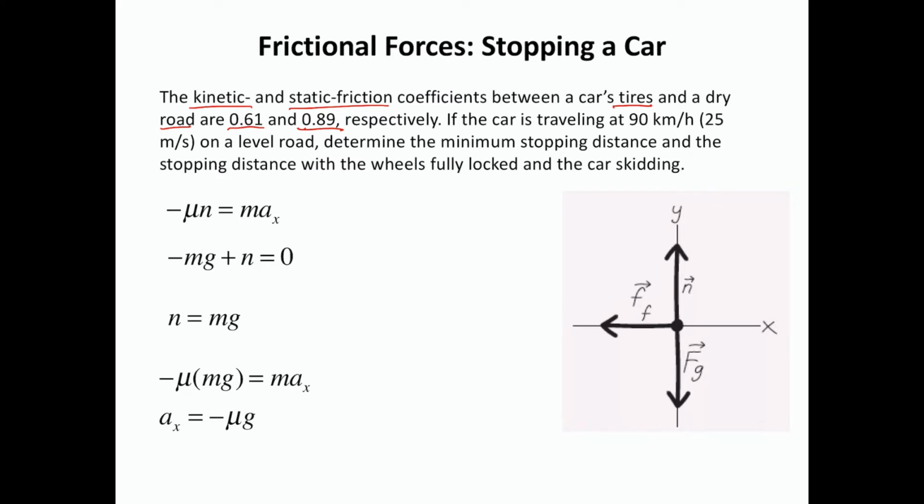If you lose the tread, the water will build up between your tire and the road with nowhere to go. And then your friction is not determined by the tire and the ground. It's determined by a layer of water. What happened? It reduces, because you got the water in between. Can you see it? So that's why enough tread on your tire is important. If the depth is not enough, it's actually against the law, you know. So it's dangerous.